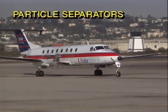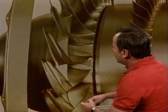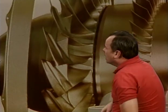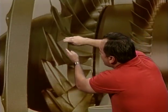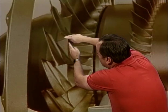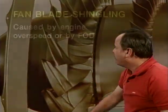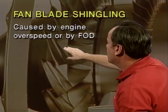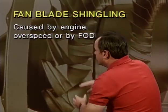Right at the front of a lot of gas turbine engines is the fan. And as you can see, these fan blades are held apart a certain distance from each other by these shrouds that go in between the blades. Well, if you have an engine overspeed or foreign object damage, these fan blades can move out of position. In order to do that, these shrouds will have to overlap, and the blades themselves can overlap a little bit, and that condition is called fan blade shingling, and it's caused by engine overspeed or by foreign object damage, and it's a bad thing. You'd have to, of course, inspect that engine very carefully.